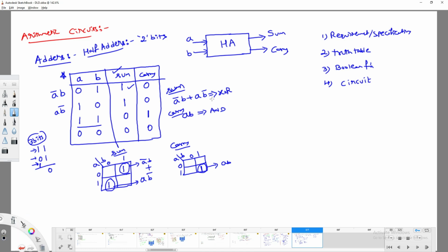So you know the inputs and the final function, right? I am going to have inputs A and B. So in order to get A bar B, what can you do? I can complement A to get A bar, and then perform the AND operation.